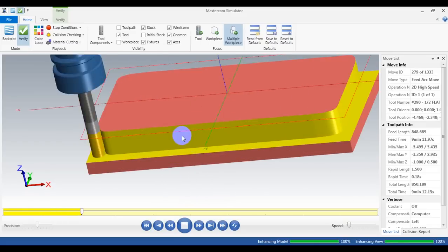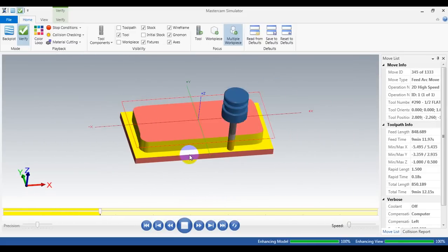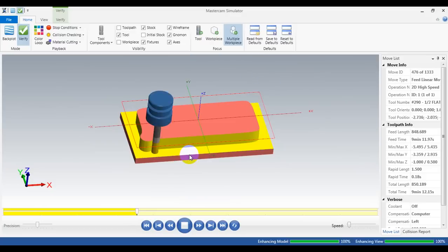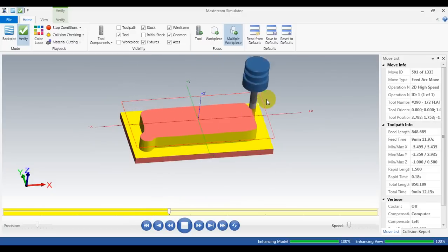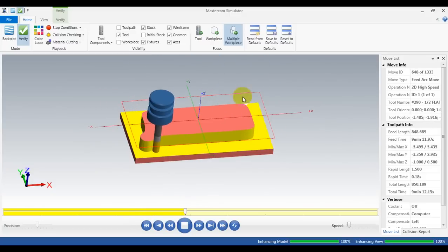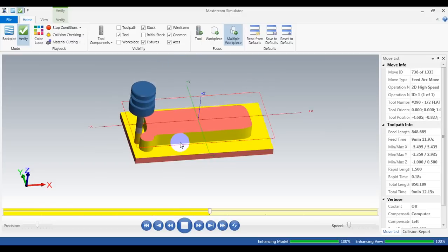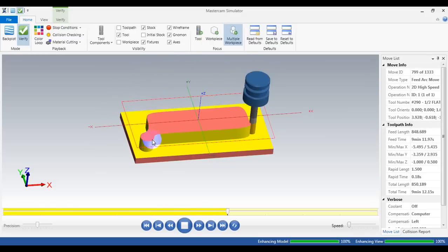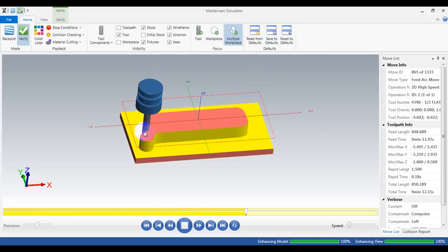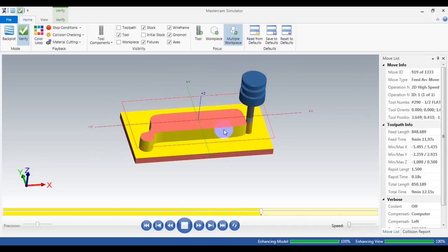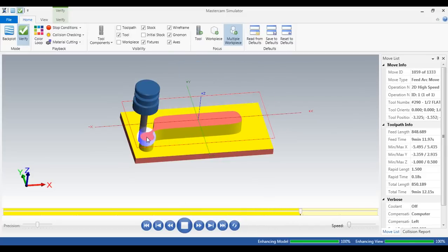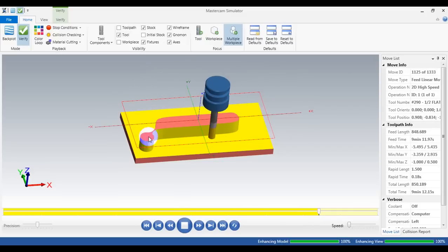This is the high speed toolpath, like in the videos you see on YouTube. You can see that we define the machining region, that's our stock boundary, and the avoidance region, that's our pin here. When calculating, Mastercam cuts the material in the machining region and leaves the material in the avoidance region.